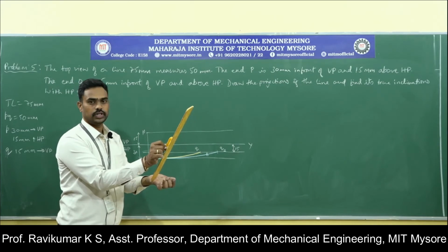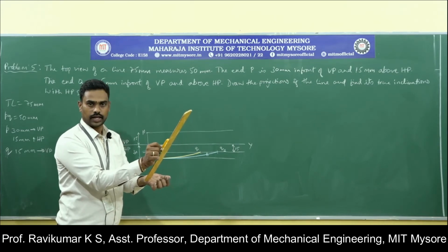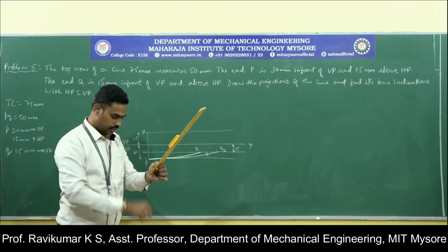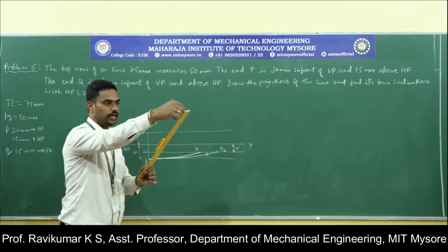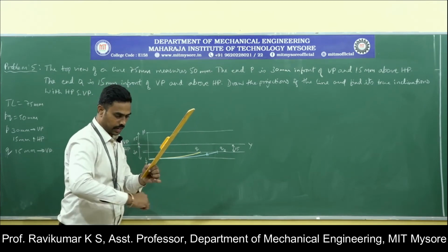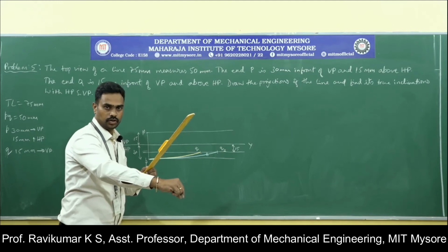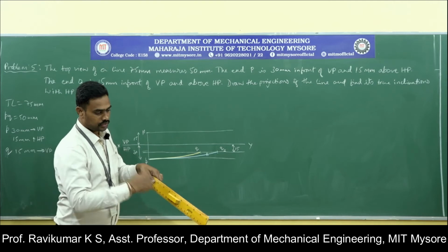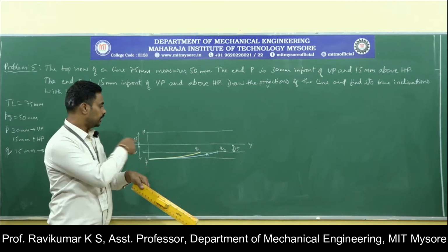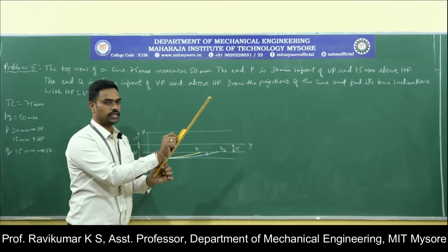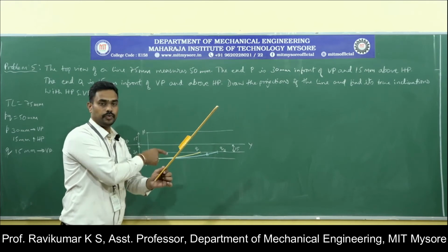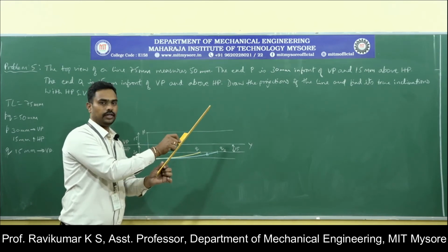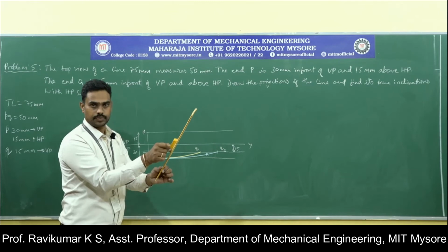So the inclination was given towards the observer, so that when you project this point and that point onto the horizontal plane and join those two points, then if you tilt it, you will get the view something like this. But in this case the inclination is given with respect to VP towards the plane like this, instead of towards the observer.